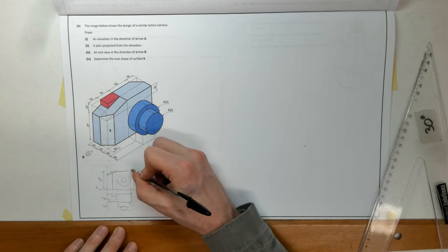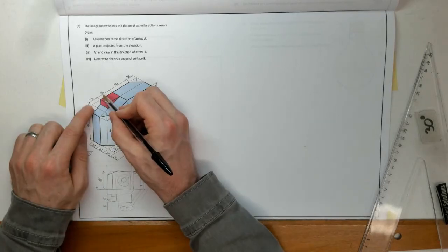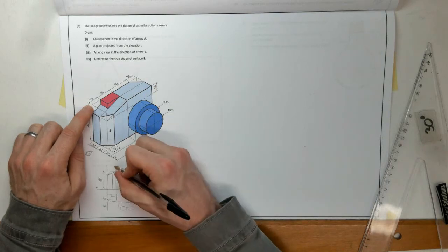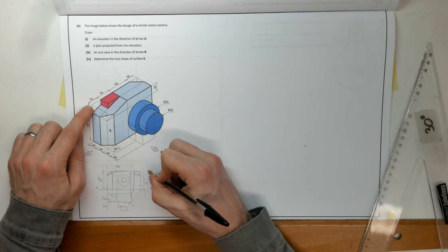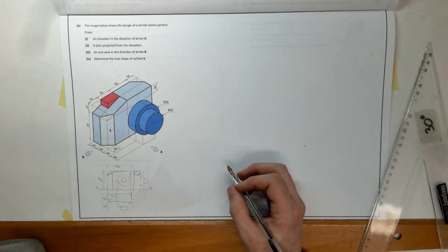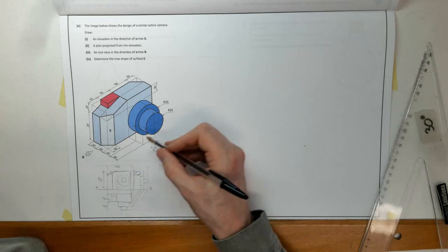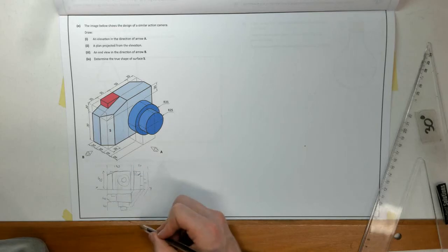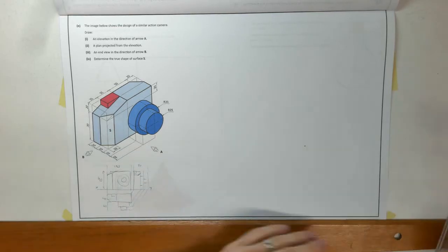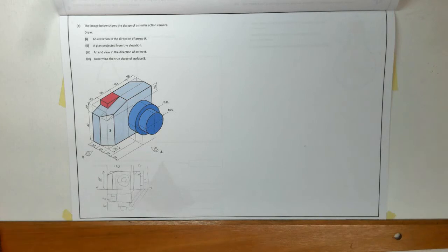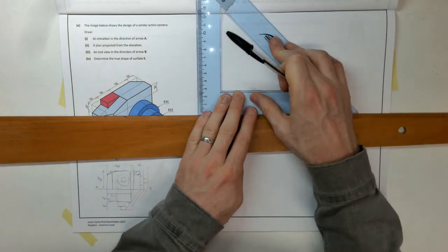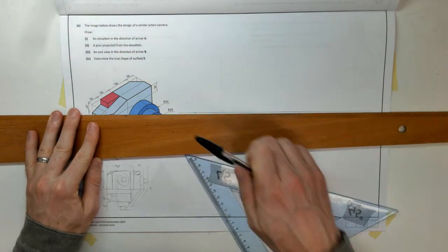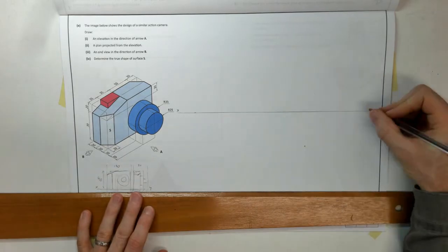So overall width, we've got 25, 35, which is 60, plus 50 is 110, plus 20, 130. And this overall width, I just do this because I can make sure I fit on the page then before I begin. So we've got the same overall width, which is going to be 80. So overall height, overall length, overall depth, we have then. So I need to come down more than 90. So if it's on the page, I'll come down 120, which should be loads. Draw my XY line. Like so, it's my X, Y.